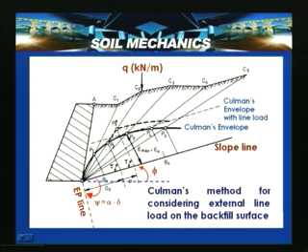So, subsequently you need to consider that load which is coming, but for a wedge, for example here, we need not consider the effect of this particular load. Only at this point when you consider it, and then subsequently when you do, the envelope changes. So, by drawing a line parallel to this surface, we will get the Coulomb's envelope here, and then we can calculate the active pressure thrust, the resultant thrust acting at a point h by 3, at a known location.